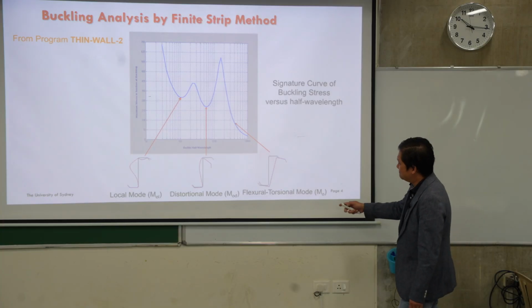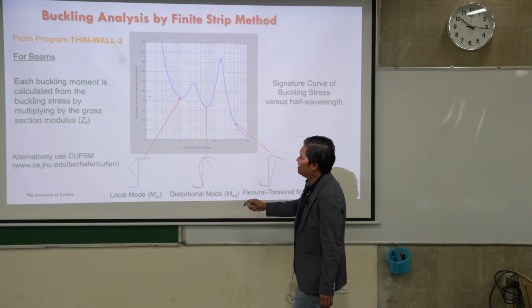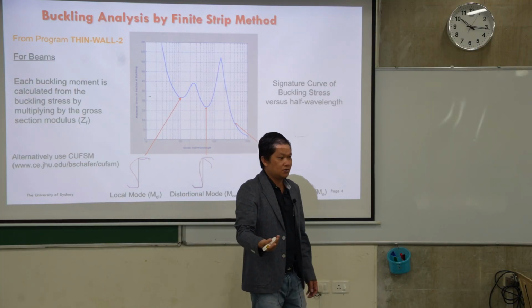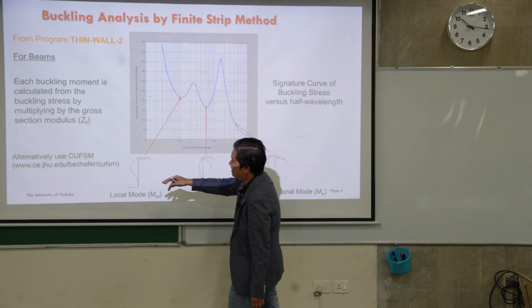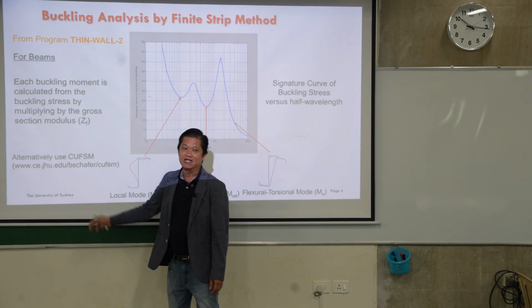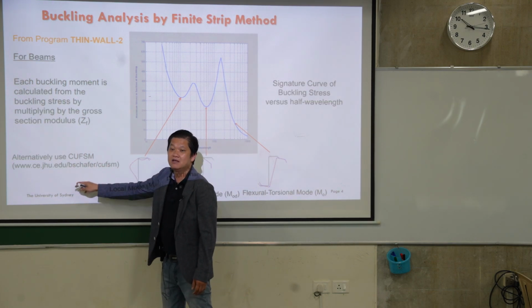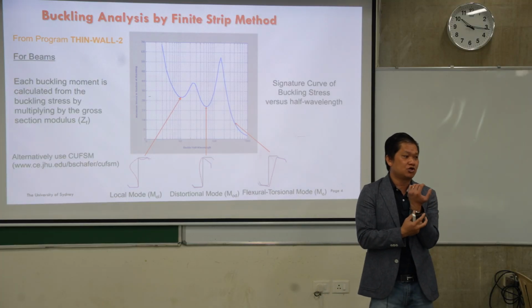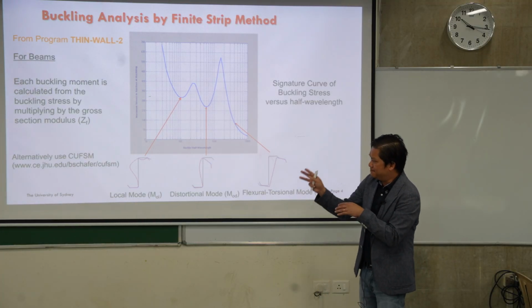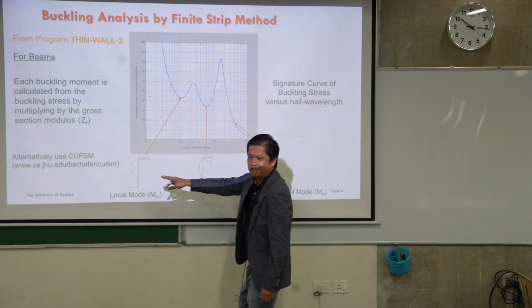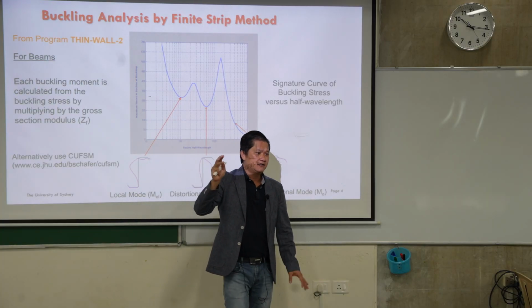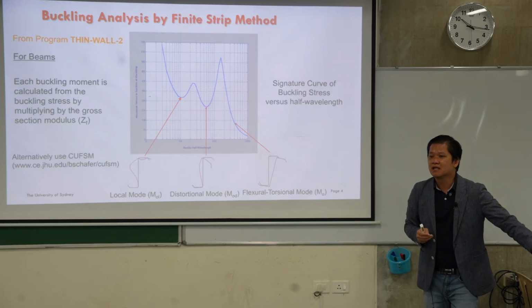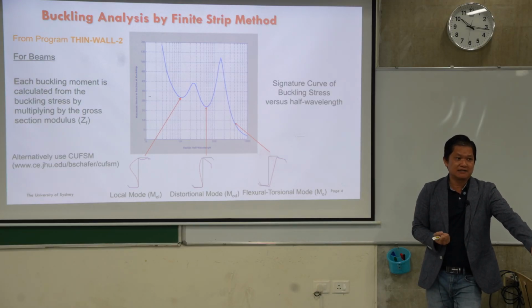Okay, so that's good. Now, you can do that using Thin-Wall, the program that I provided to you. Or alternately, you can use CUFSM. It's developed by Professor Ben Schafer at Johns Hopkins. As I mentioned before, they are very similar, just a different interface, depending on how we design. But the engine behind it is all based on the finite strip method.